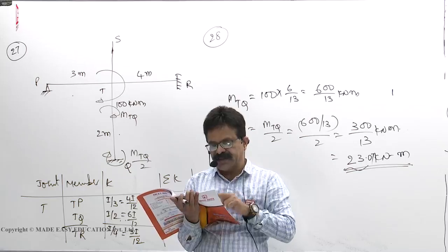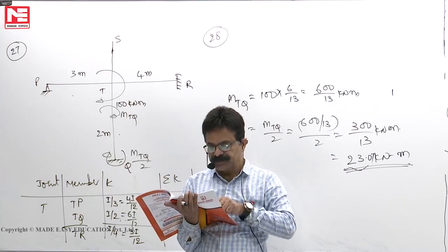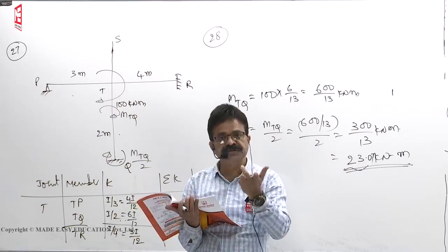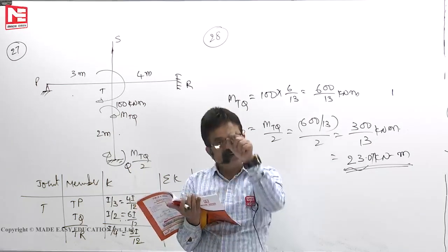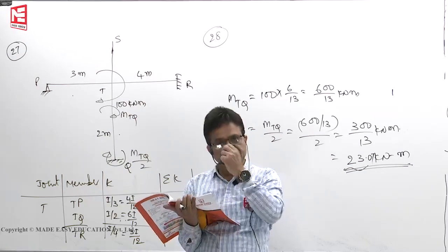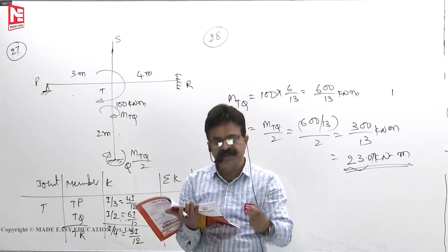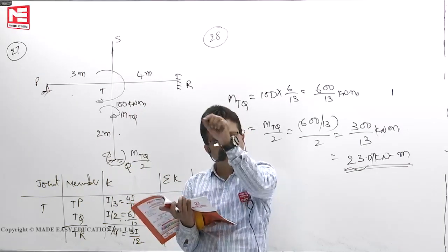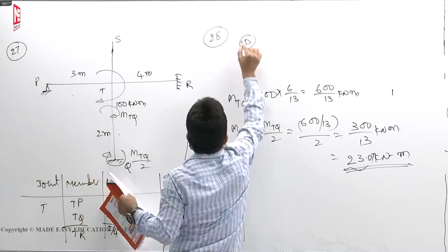Next, D: because of the carry-over concept, there is one point of contraflexure, correct. Then at the left corner, 2 moments they have shown, of the same magnitude. UDL was there, diagram given. At the right end there is a hinge, so bending moment is 0, as they have shown. So all points are satisfied. There is one point of contraflexure because of the carry-over concept. Moments at the joint, the 2 moments on the beam and column at that joint are equal. So with this condition, D is the option.